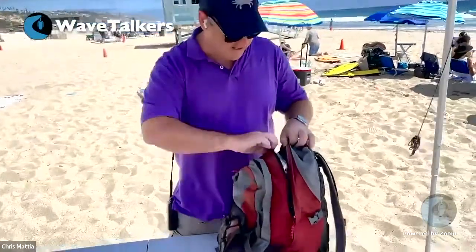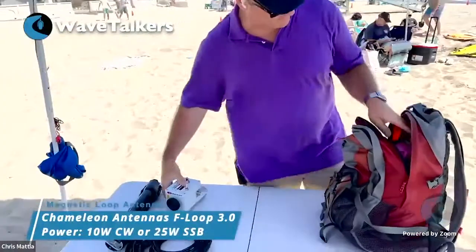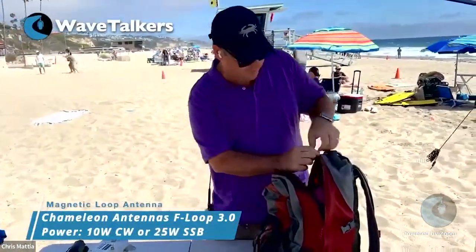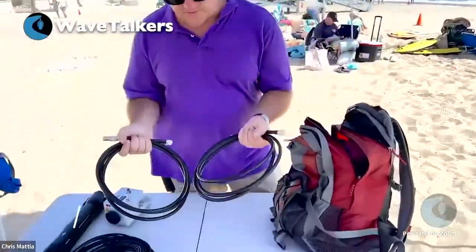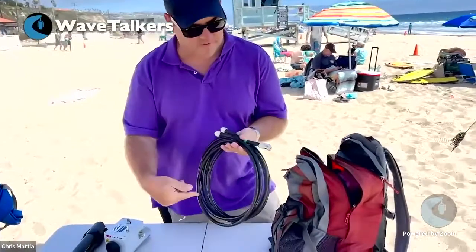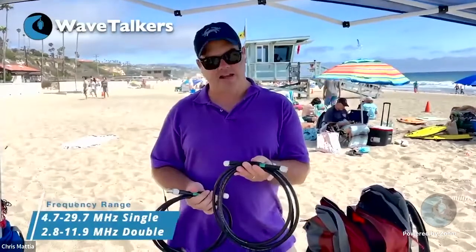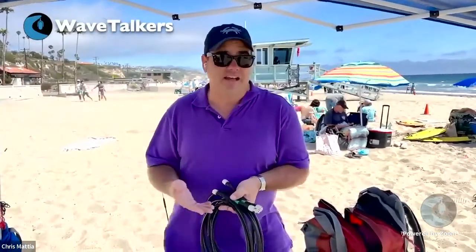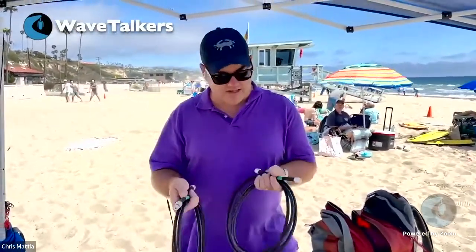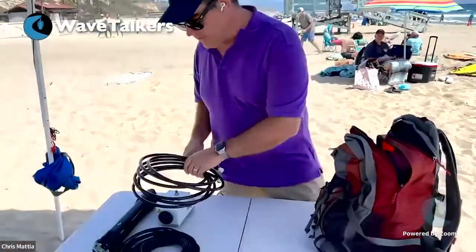Let's go into the main pocket here. This is the matching unit for the F-Loop 3.0. And back in the back portion of it, I have two loops back here. And these two loops, these are shorted loops of LMR 400 coax. And you put one loop on, you can operate on some of the higher HF bands. If you connect the two loops together, there's a coupler here. You can connect the two loops together and you get down to 8 meters. So depending on the needs of the band that you're going to operate with, you can connect one or two of these loops and just connect them onto the F-Loop base. We'll look at that in a little while as well.